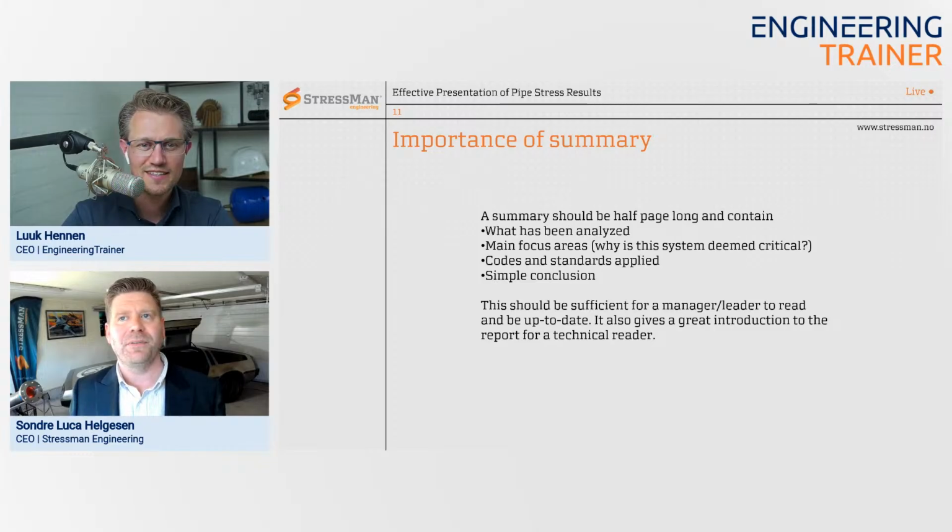But if the assumptions are on the conservative side, and in many cases we put in assumptions that are not totally validated, we also know that what we are doing is conservative. For example, we sometimes do hydrogen-induced stress cracking in accordance with DNV-RP-F112, and there are some factors in there.